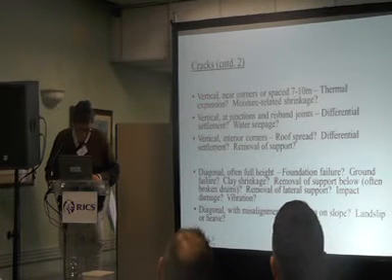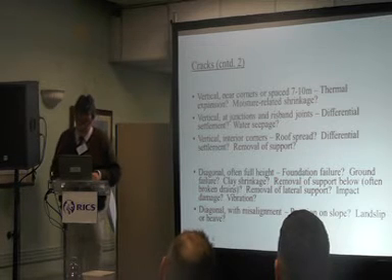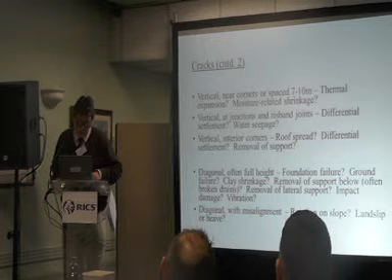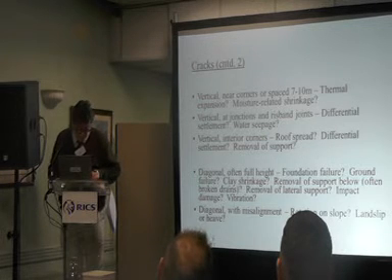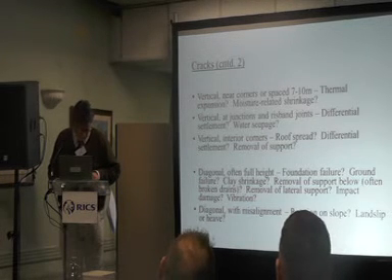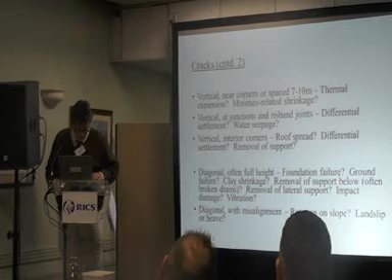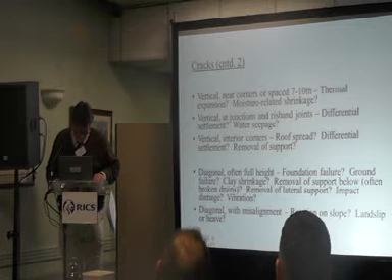Impact damage, surprisingly common actually, and vibration. When you find cracking, particularly diagonal cracking, we're working on a building on a main road in Richmond, Yorkshire, and it's 400 years old, and we're finding cracks due to vibration. The building wasn't built for the kind of vibration it's getting these days. Diagonal with misalignment, you start looking for rotation on slopes, landslip and heave.